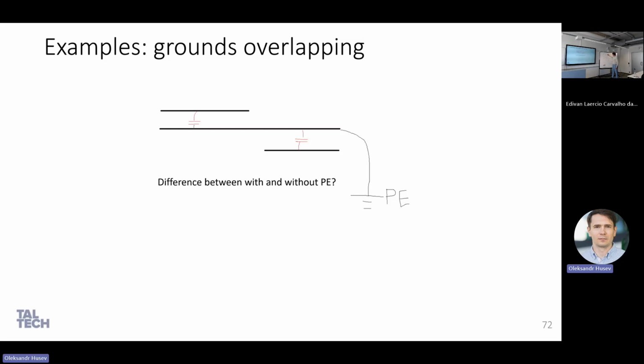And you have a second winding, which you connected to this fourth layer or third layer. Here are some other parts and so on. You know that you need to avoid overlapping, otherwise you will create additional capacitors. And you have a plane here, and a plane here. They are not overlapped, so the capacitor is fine.